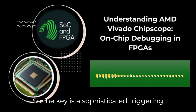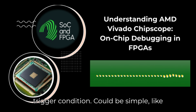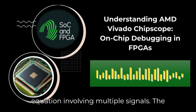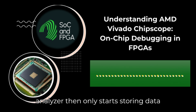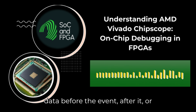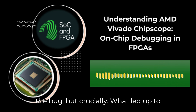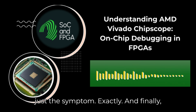So the key is a sophisticated triggering mechanism. The designer configures a trigger condition. Could be simple, like a signal changing, or a complex Boolean equation involving multiple signals. The analyzer then only starts storing data when that specific condition is met. And you can position the trigger, capture data before the event, after it, or centered around it. So you see not just the bug, but crucially, what led up to it. That's powerful, seeing the cause, not just the symptom.